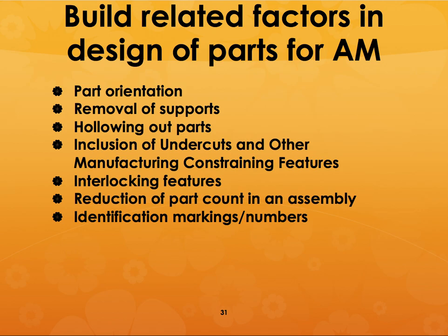You need to be able to build up the supports, and then after the part is built, you need to figure out how to remove those supports. And sometimes you may not be able to build hollowed out areas, so you may have to do that afterwards. And how you include undercuts and other manufacturing constraining features, etc., is going to control your final part that is built by additive manufacturing.